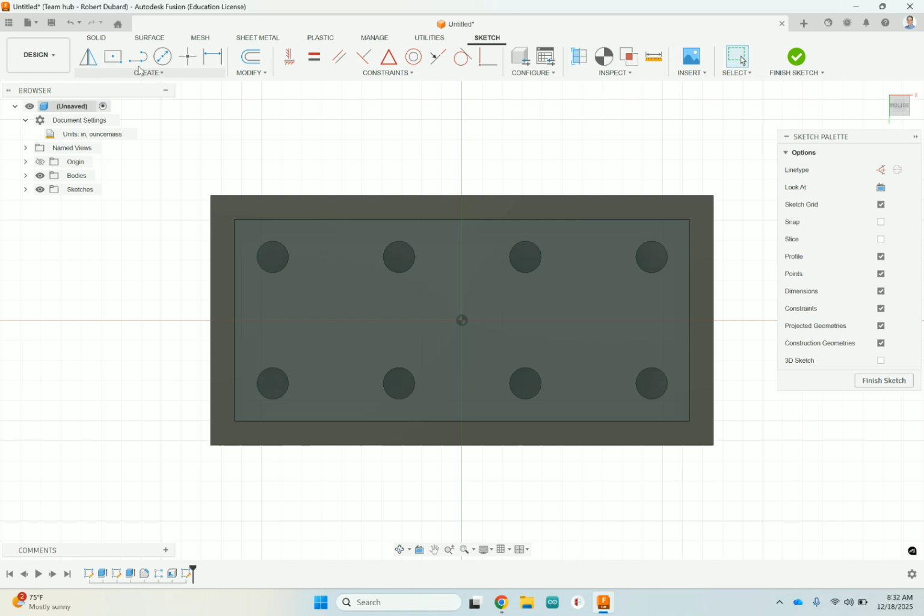And what we're going to do is go up here and create a line. Now this line, I'm going to change the type of. It's the first time we've done this. When you open a sketch tool of any kind, there's always a sketch palette over here. And usually I ignore it and just make my sketch. But this time we're going to change the line type to construction. For now, don't worry too much about what a construction line is, but it is the proper line type for what we're about to do. Okay, so create a line of type construction.